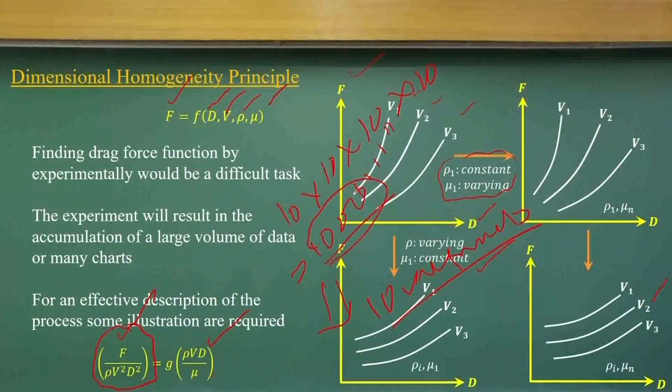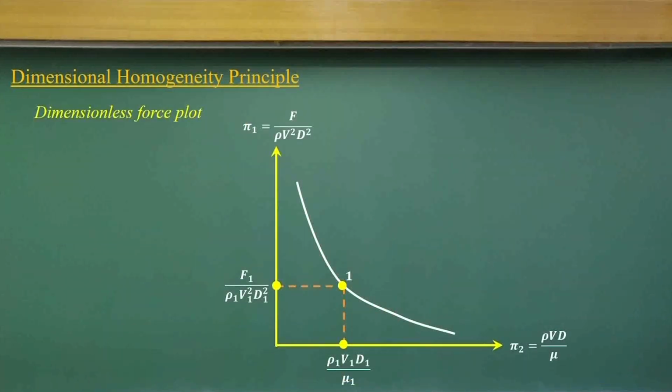So what I have developed now, instead of the F function, is a g function, which is a relationship between 2 non-dimensional groups, one on the left side and one on the right side. I should conduct experiments at different Reynolds numbers, get the force from the experiment, non-dimensionalize it as an f1 function, and fit a function to the data.